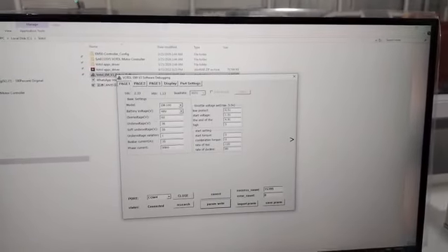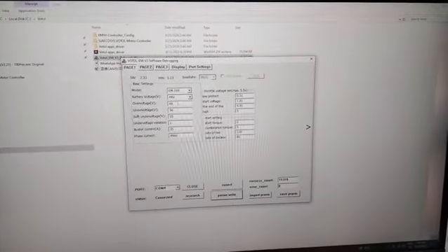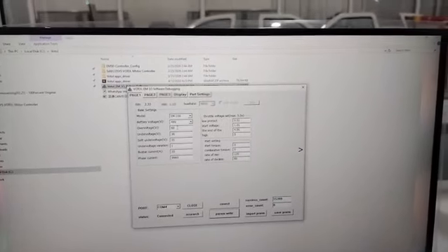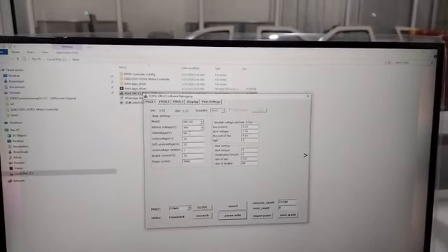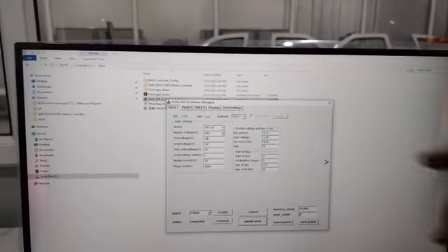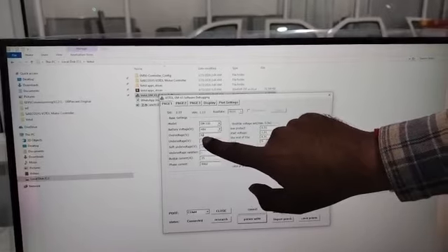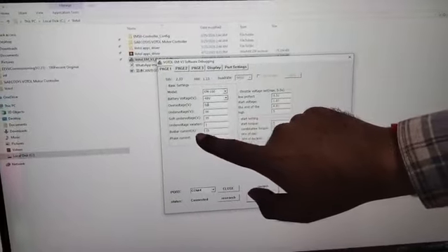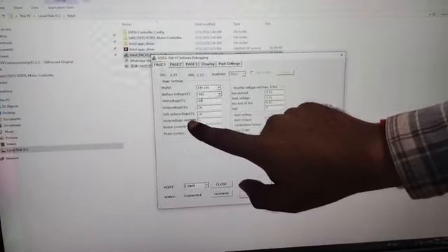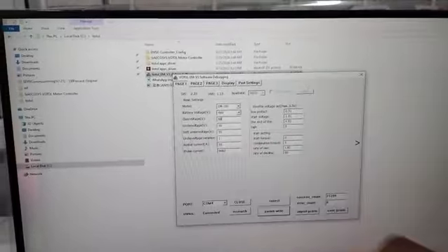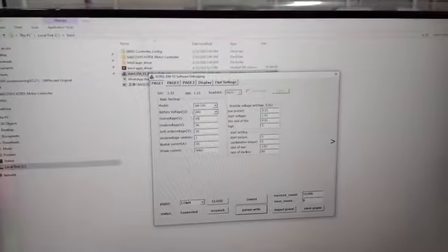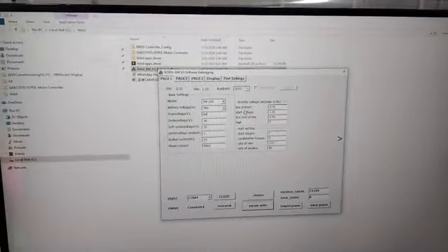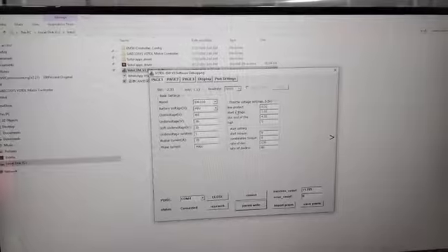We check here the under voltage and over voltage fault, which is automatically organized. Basically we have manually organized this. So this is the under voltage and over voltage fault. Here is the bus bar current. Here is the voltage variation for the under voltage and over voltage fault, and here is the phase current. So this is the basic factor we have to tune in a hub motor.